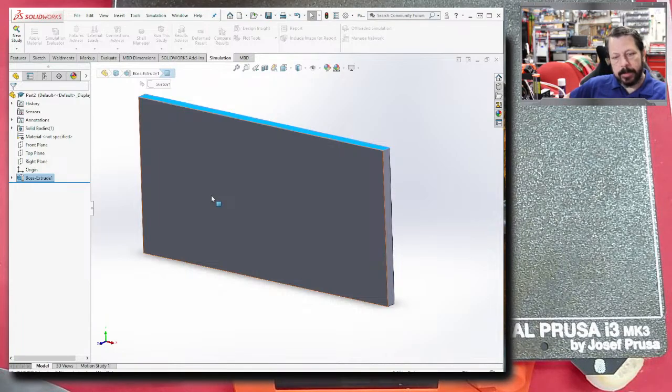Like I said, the model that comes out of the SolidWorks one is really just a template. You could print it, but it's going to be very unattractive looking typically. So normally what you do is you take that model as a template and create a new model around it, using the guidelines of where it reduced area, and you just create a smaller area or smaller thickness in your model in that spot.